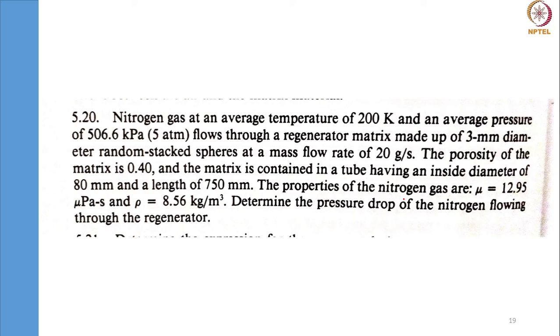For finding out the pressure drop, I'll give you a correlation based on the friction factor: friction factor f is 5.375 times Reynolds number to the power minus 0.14.